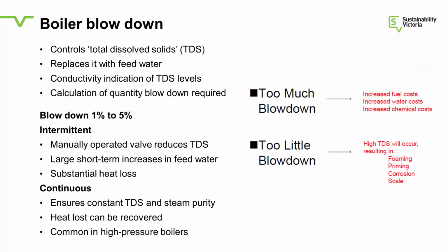Okay, boiler blowdown. I mentioned boiler blowdown before. Basically, there's a thing called total dissolved solids. In any water, solids build up in the water. They're a dissolved solid, but they can cause damage to the boiler. So you need to get rid of that total dissolved solids to keep your water quality up. To do that, they do blowdown.